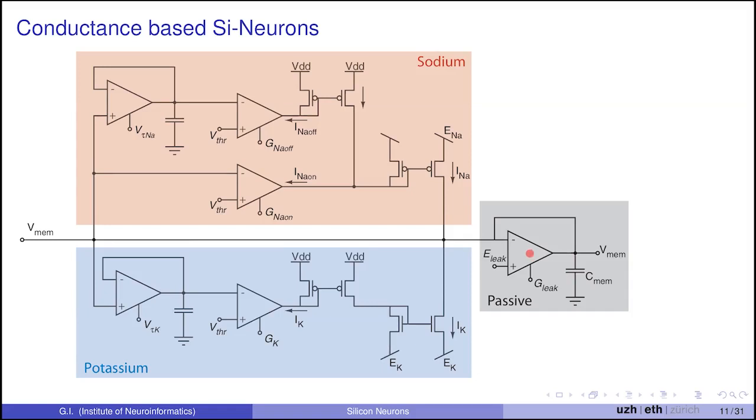The other disadvantage of the circuit is the fact that we're using sub-threshold analog circuits and many transistors. And you know that analog circuits are affected by device mismatch. So even though you can copy paste the layout of these circuits and in theory have identical copies, when you fabricate these chips, there will be differences in the voltage thresholds of the transistors, in the geometry.